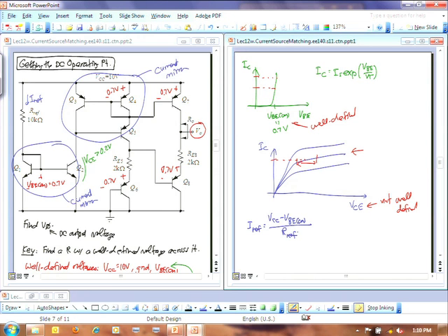And then I can look at this. Oh, this is a current mirror, so that current right there is also IREF. It should have a nice large output resistance there. It should be shoving IREF through that device as well. Okay? And then I look at this. Oh, there's another current mirror right here. So this current, it's also IREF. So one little equation has given me the current through all these branches here.